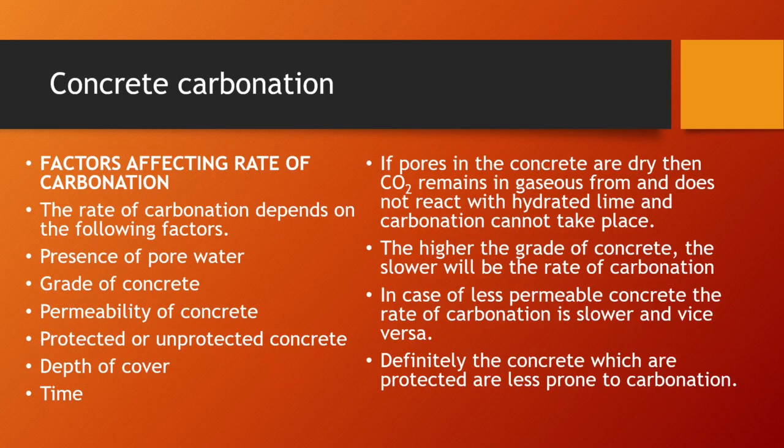The higher the grade of the concrete, the slower the rate of carbonation. So big infrastructure buildings using C50, for instance, have much slower carbonation. And of course, when we talk about the drying time, it depends on how much carbonation takes place and how much reaction has taken place with hydrated lime. And definitely the concrete which is protected is less prone to carbonation.